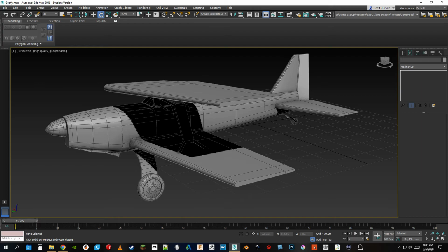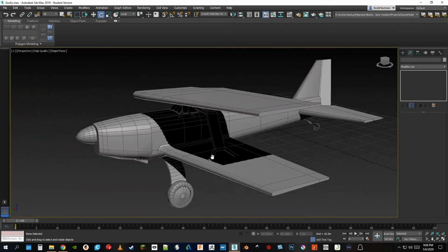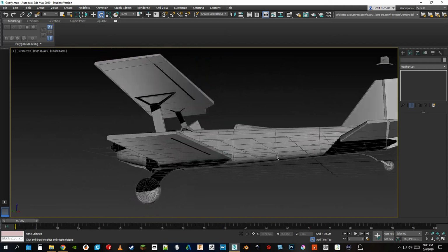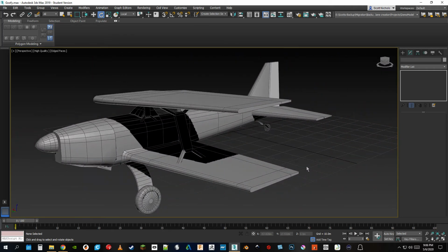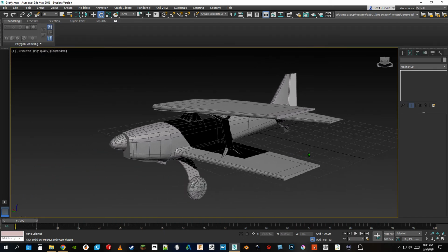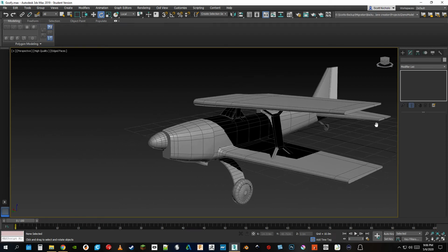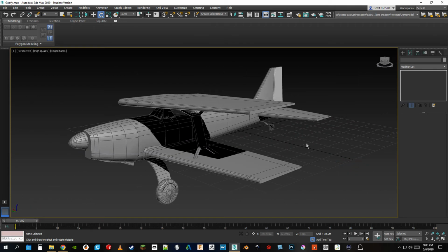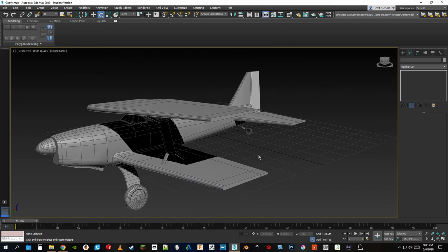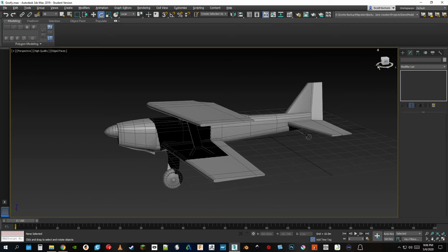because some of the controls that we can use would be to use your middle mouse button, click anywhere, and you'll pan around. You'll move the model around, panning. If you hold that same middle mouse button and hold Alt, you'll get a rotation. And if you middle mouse button and hit Control and Alt and move your mouse forward and back, you can zoom in and out. And if you hold Shift, you can lock movement in an axis. The first axis you move in will be the one you lock in. So Shift and move in a direction, and it gets locked in. So between these types, that's all the manipulation you really need.